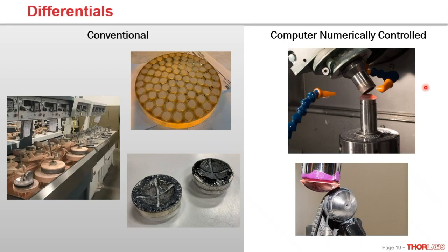We see first inside one of the CNC machines, where one of the lenses or items that were our workpiece here is fixtured up into the machine, where we then have our additional axes of rotation that are brought in so that we can contact at a surface, which allows for, as we discussed, some of the unique capabilities of the CNC. And then just some additional nozzles for supplying the coolant to the surface as it grinds or polishes.